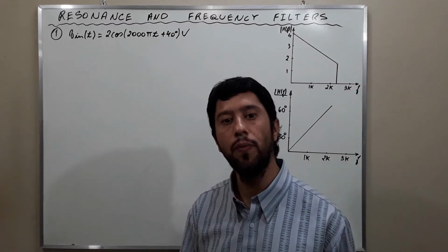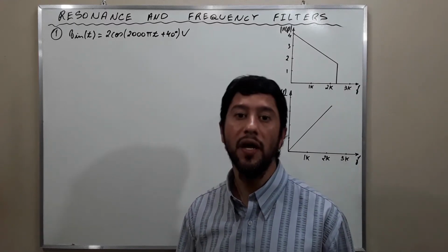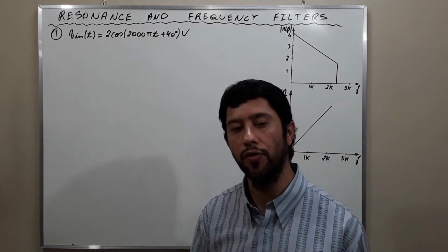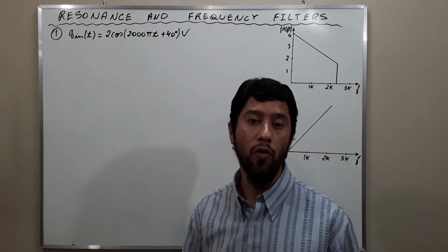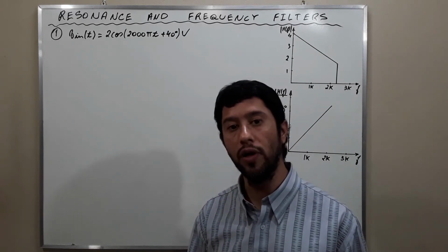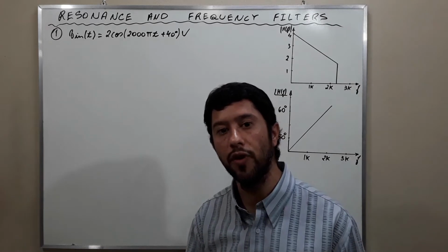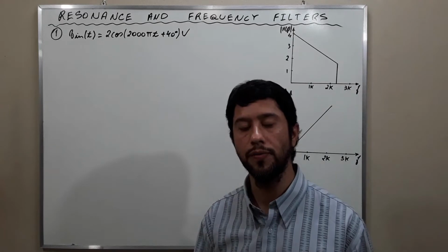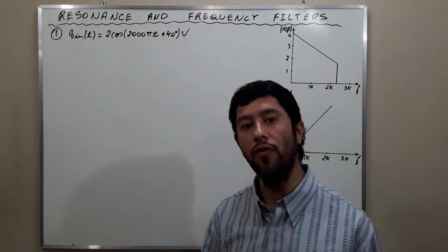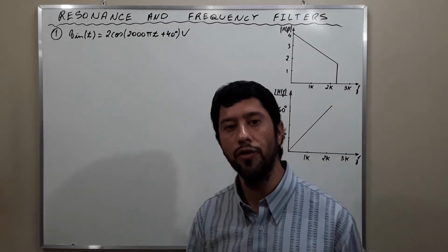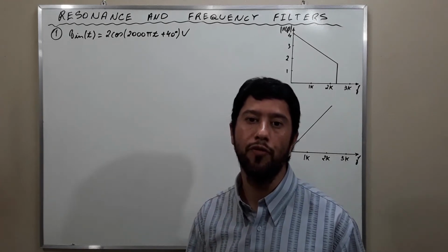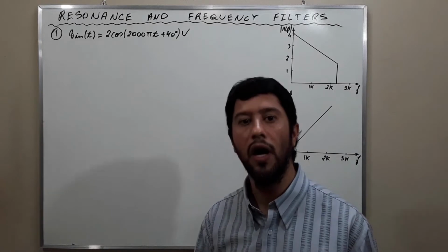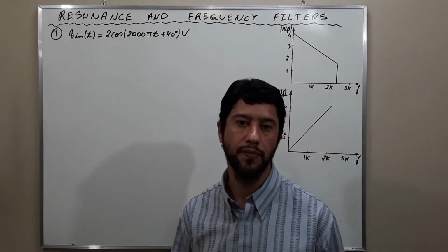Filter circuits are two-port networks. The signal to be filtered is applied to the input terminals, and only the components in the frequency range of interest appear at the output terminals. The phenomenon of resonance is used to improve the performance of filters in rejecting unwanted signals.